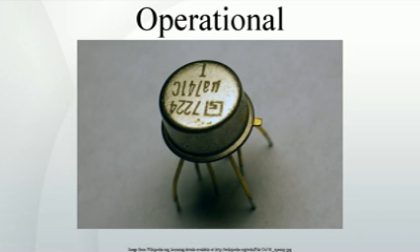If the voltage to be sensed, V_I, is applied to the op-amp's plus input, the result is a non-inverting positive level detector. When V_I is above V_REF, V_O equals plus V_SAT. When V_I is below V_REF, V_O equals minus V_SAT. If V_I is applied to the inverting input, the circuit is an inverting positive level detector. When V_I is above V_REF, V_O equals minus V_SAT.